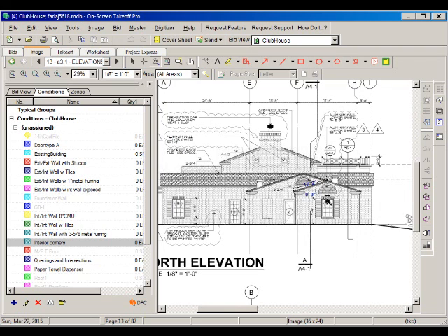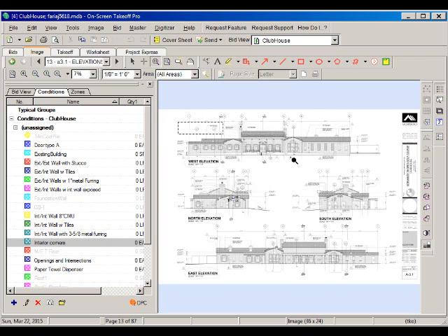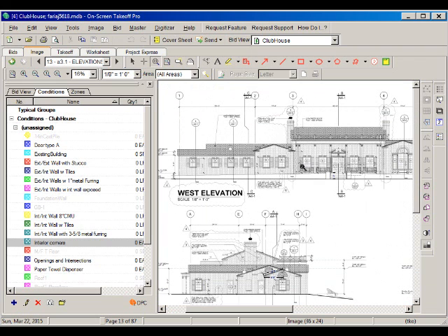As we can see in the north elevation, this north area is slightly lower than the central corridor, which is lower than the main entrance of the building. So that indication shows that we will need to create different conditions for the walls that are on the low height, medium height, and high height. So we will need to have conditions for each one of those different types.